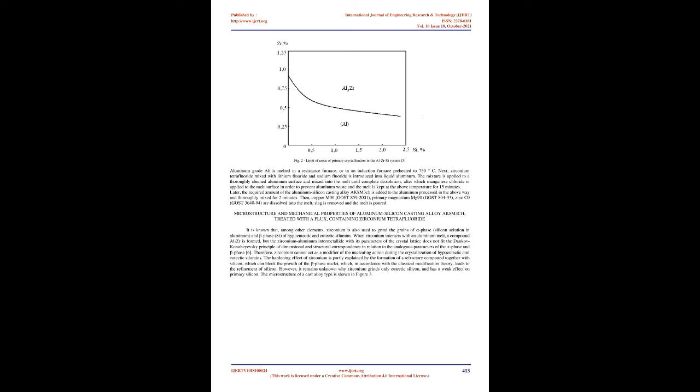Methodology. In order to study the microstructure and mechanical properties of the cast alloy of the Al-Si-Cu-Mg system, treated with compound flux containing zirconium tetrafluoride, the AK8M3ch alloy was chosen. One of the tasks of the work was to find a replacement for beryllium, used as an alloying component of this alloy. The closest analogues of this alloy are alloys A380.0, US ASTM standard, SG84A, US B85 standard, and GD-AlSi9Cu3, German DIN 1725 T.2 standard.